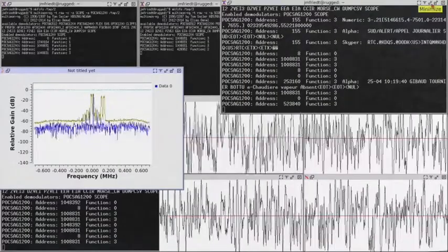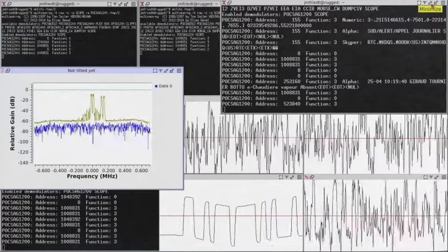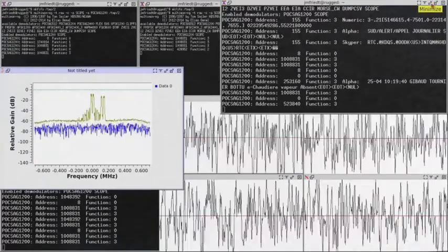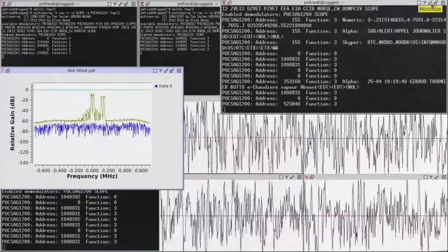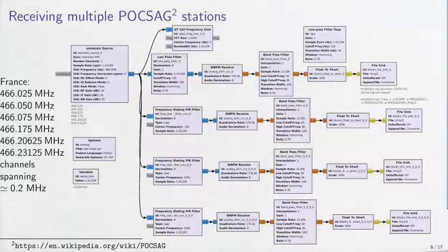So here is the last message being decoded in this instance, with the decoding on the top right terminal. This demonstrates multi-channel analysis, in this example using POCSAG and the pager, which is quite feasible because these are low bandwidth messages, low bandwidth protocols that do not require much processing power.